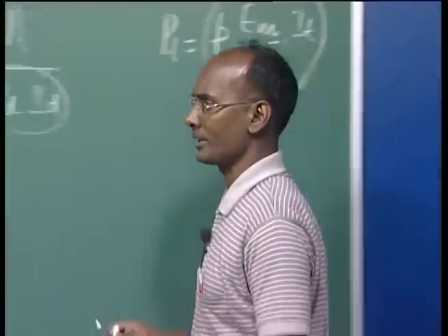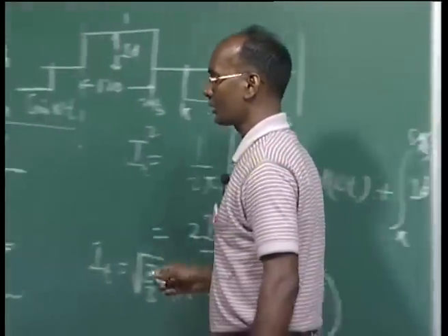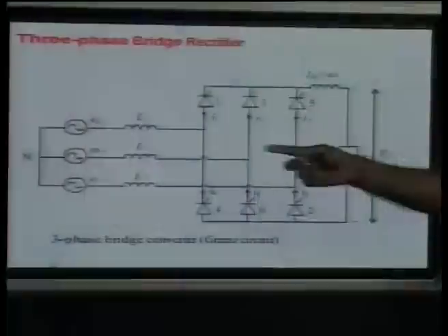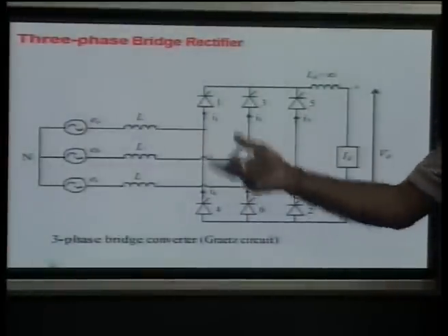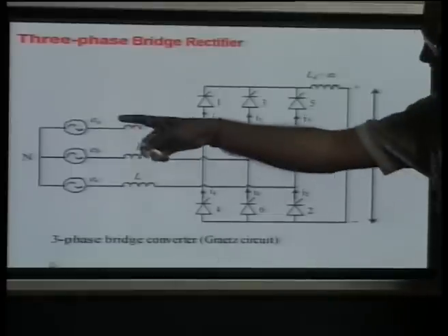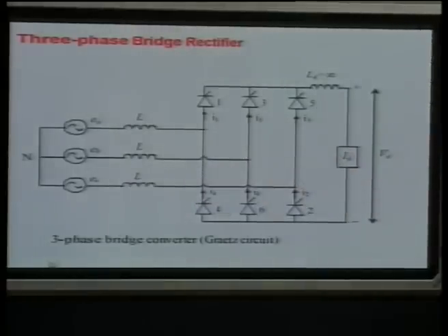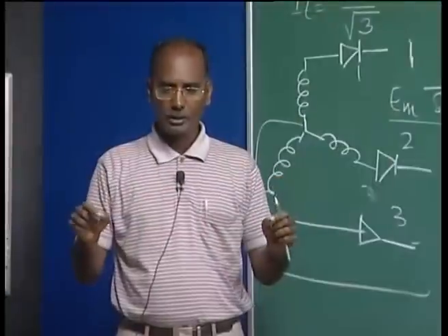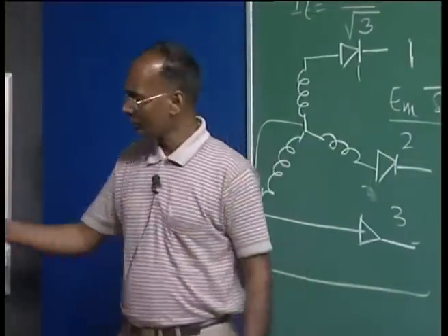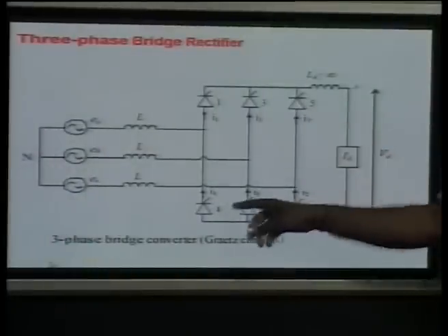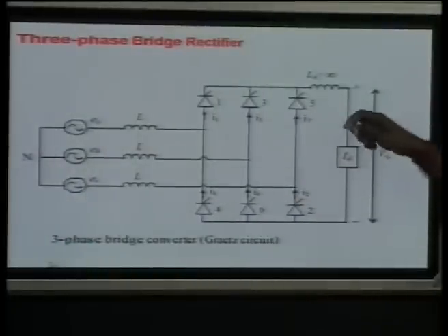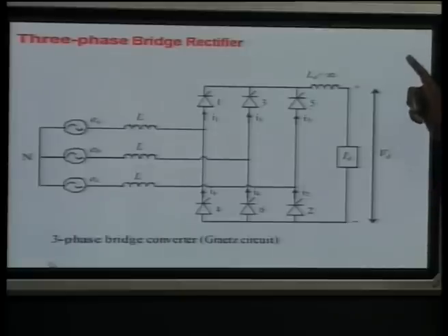Here this is the circuit. Now, we have to analyze this circuit, and in this analysis it is assumed that the inductance, this is the winding inductance here, but this value is very insignificant. We are having the balanced 3 phases on the secondary side, and the numbers are made in such a way that we will see the conduction pattern in the symmetrical order, so that there is no need to remember. That is why 1, 3, 5, 4, 6, 2 are denoted, and it is assumed, as I said, that the DC current is constant in this link.